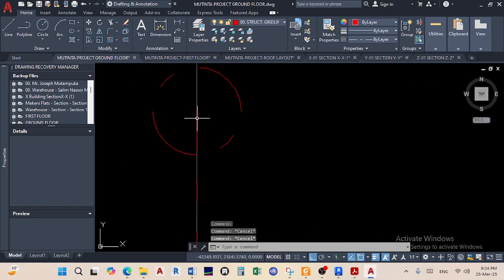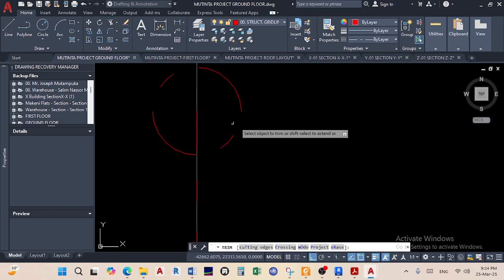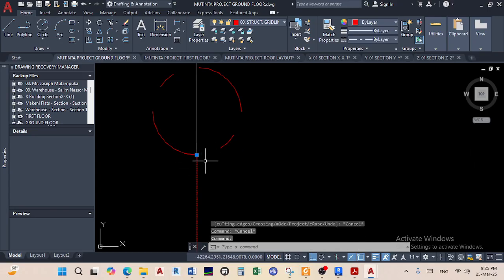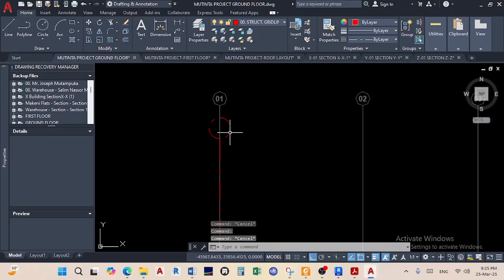But as you can see here, it's extending. I can either drag it down all the way like that, or I could have trimmed it, let me control Z. So I could have used this other tool, the trim. Once I select it, I right click, enter, and then when I do that, it also brings it right there at the bottom. Both work the same.